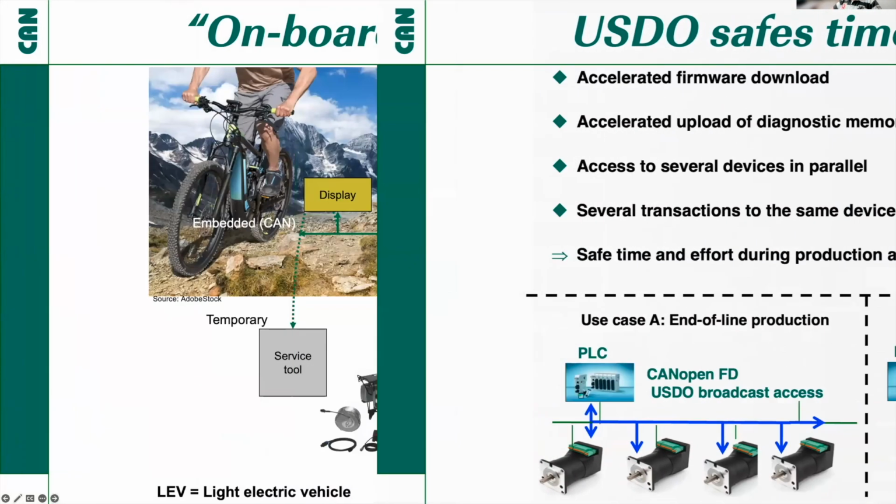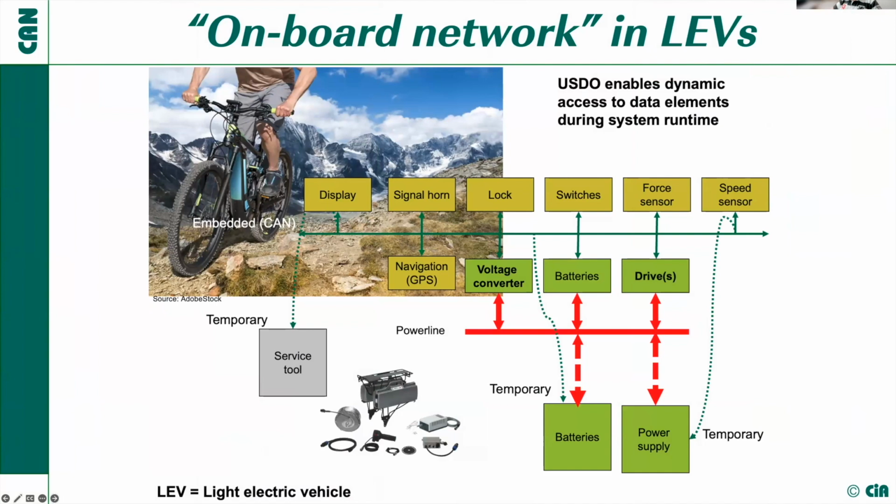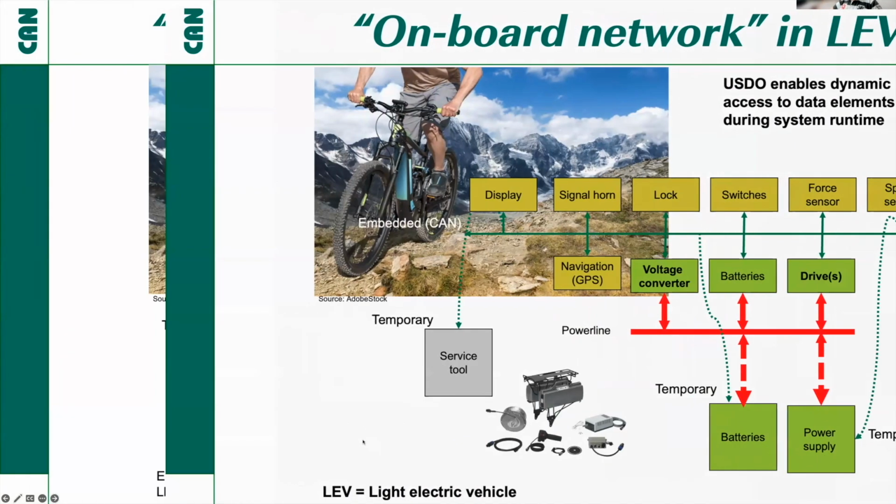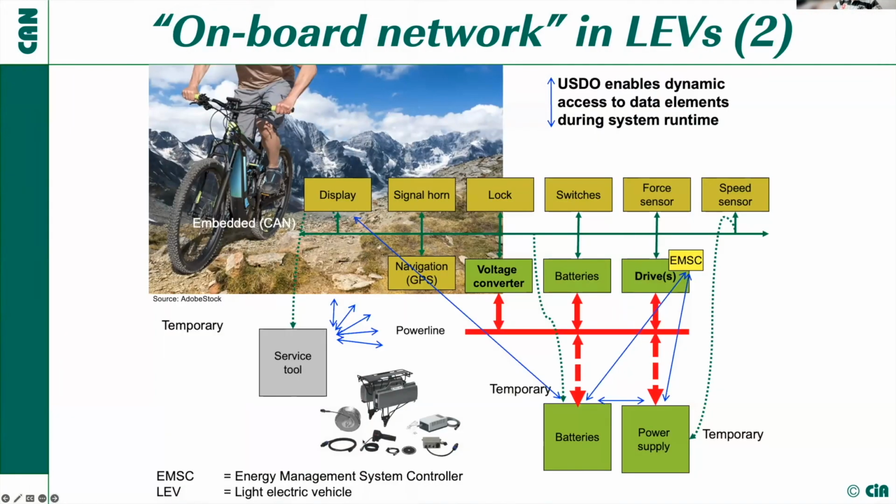And I can also support dynamically changing systems. So I have here, for example, a Pedelec, which has an onboard network. This is a very good example of an application where the end user is modifying something and you need to immediately set up dynamic communication channels. A host controller managing the entire bike needs to have dynamic access to newly attached devices and has to get familiar with them. Are they allowed to act here? And then he can treat them accordingly.